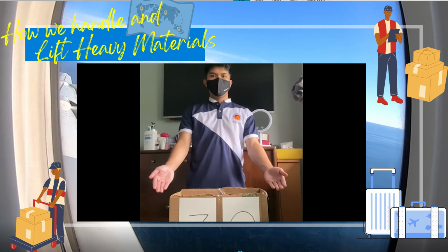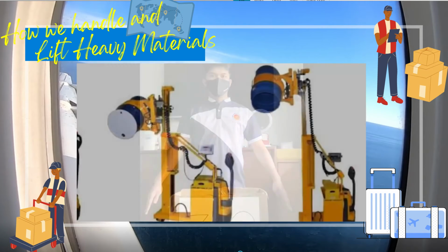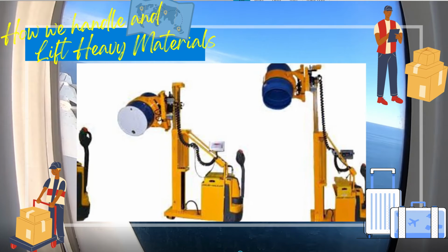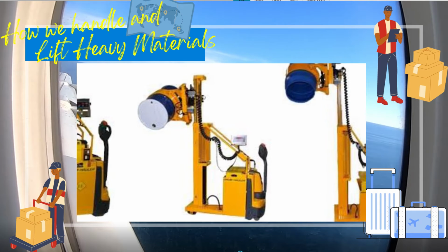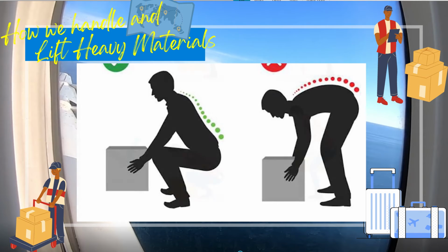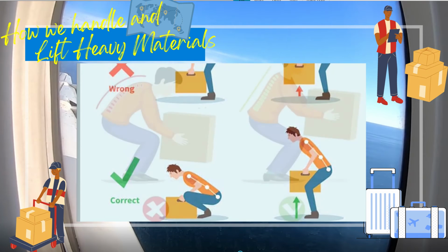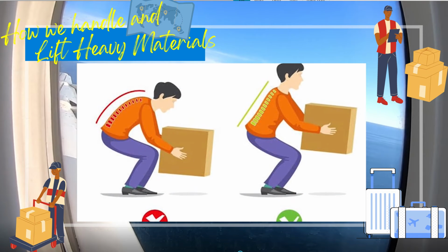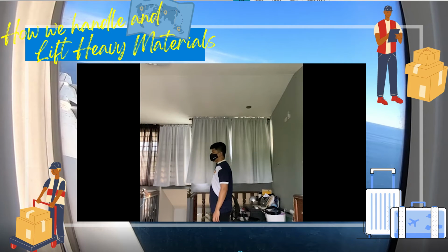Generally, if a load is heavier than about 50 pounds, do not attempt to lift it manually. Use a lifting device, such as a powered barrel dumper, to lift loads deemed too heavy for workers. Using proper lifting techniques when performing manual lifts will minimize the risk of injuries to the back, OSHA states. When lifting, follow these tips to stay safe. Try to maintain a neutral spine alignment. Typically, bending at the knees, not the waist, will help maintain proper spine health.